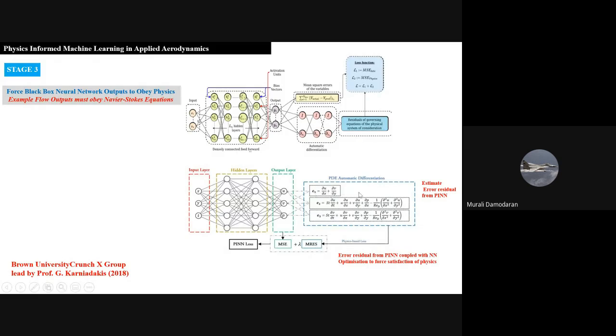These all go to zero, because those are the PDEs for the flow. So you'll have an error. You take the square of the error, and that is called the residual physics-based loss. I put a lambda here. In most of the papers, lambda is usually 1, but this is a parameter you can play around with. And then you do this.